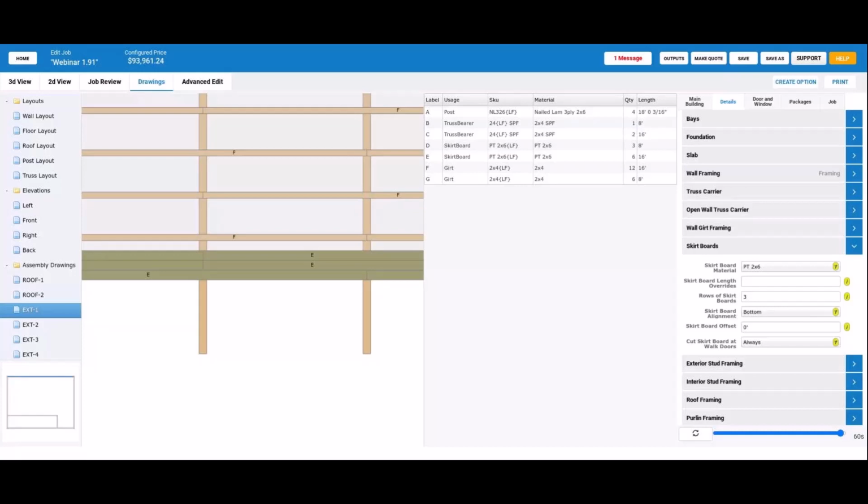No. You could do that, but they're not always below grade. Yeah, but that's the concept. Anyway, these are kind of details we've gotta flesh out. I mean, you want them to be pressure treated if any portion of it is below grade. Well, it's not below grade, it's above grade, but they piled dirt up on it.